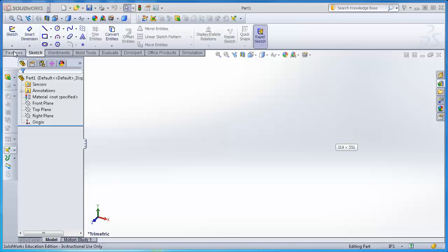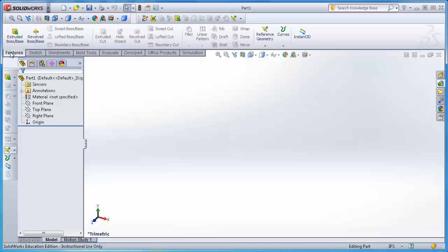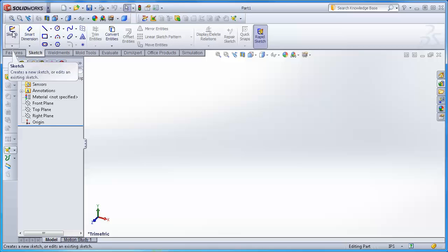The various things we'll create, a cut, a piece of solid, would be called features. Under the feature menu, we have highlighted really the only few things that we can create right now. It would be either a straight line extruded boss or base, as it's called, or a revolved about an axis boss or base. We could start by clicking on extrude, but most features, extrude would then lead us straight to sketch. Or we could just start with sketch by creating a sketch and then move on to the extrude. That's more my habit. So I'm going to go ahead and create the sketch.